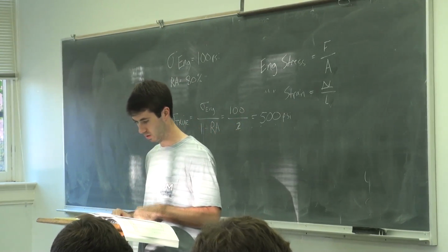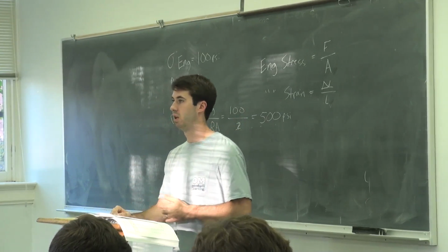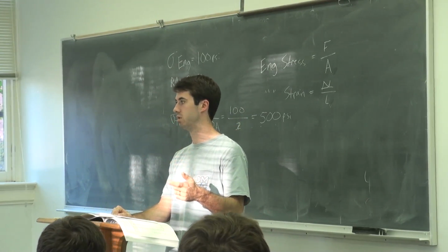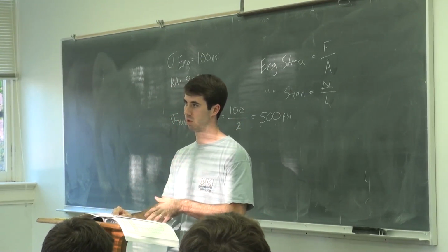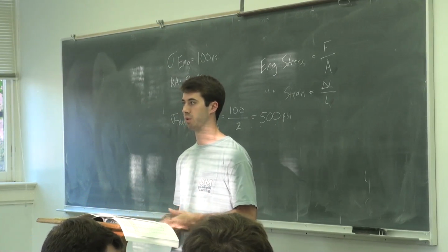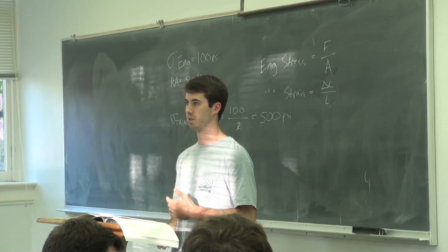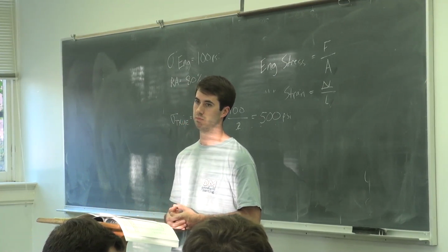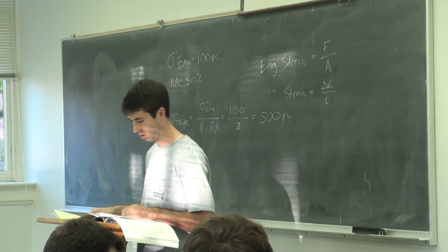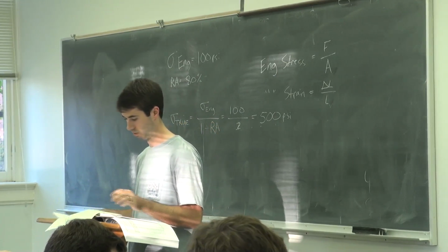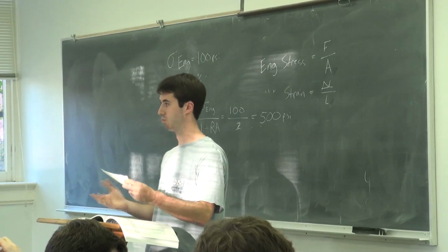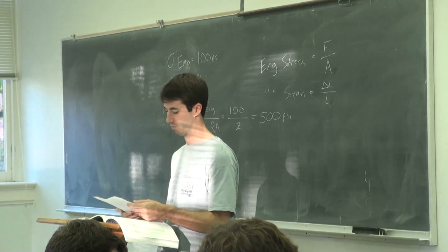And then, this only deals with everything above the subgrade. The structural number, like I said, is to protect the subgrade. So your subgrade and traffic would tell you what your structural number needed to be. You would go through and adjust all your layer thicknesses until you calculated a structural number that was greater than what you needed. So that is pretty simple. Would you say that A number is typically 0.11, 0.14, 0.44?